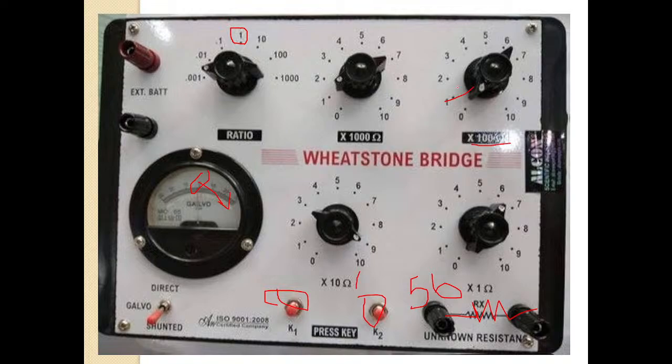And when I further increase this resistance to 200 ohms, and my deflection is gradually increasing towards the right side, then I must bring it back to the initial zero position, and I must try some other knob, maybe 1000, or let me check some lower value. Okay, 10 ohms is there, so I will set 10 into 1, and if the deflection is low, I will better prefer this knob.